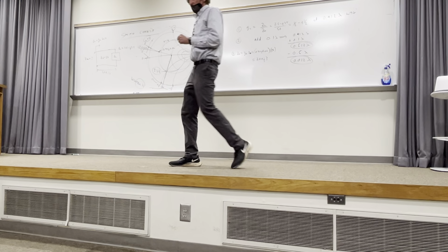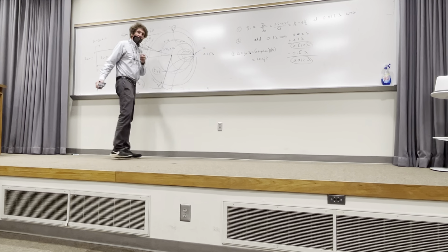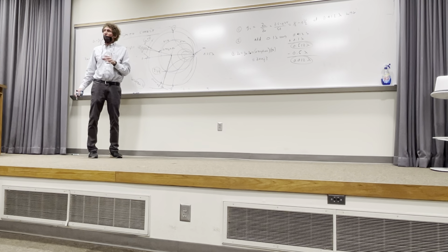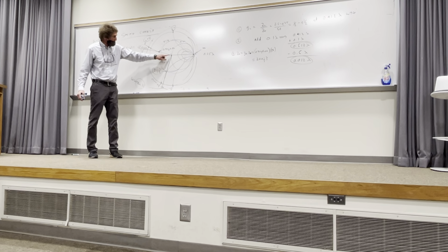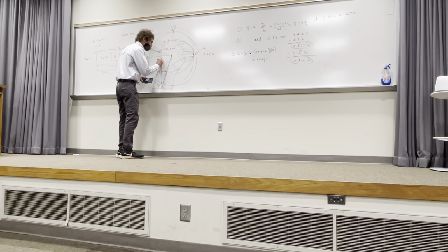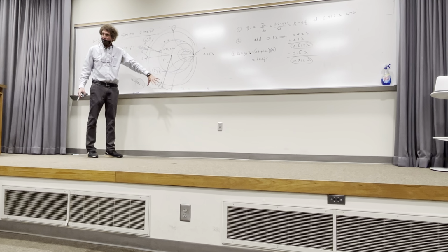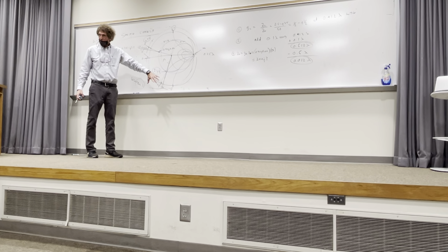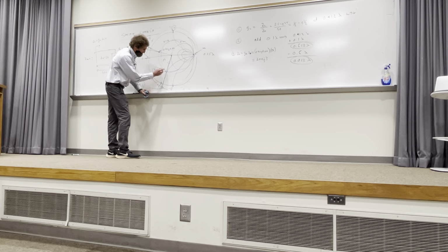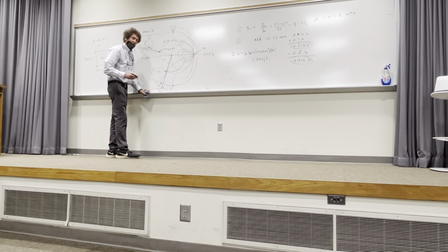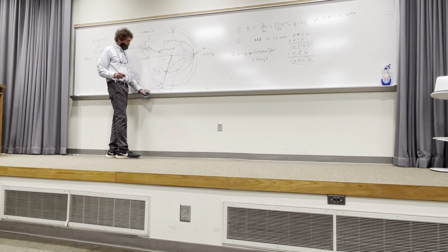What would the VSWR be using this? First, just remember, we got VSWR, standing wave ratio, right? And I think we got reflection coefficient. Now, this length right here, that is the length of the reflection coefficient. If you take it and then measure it against the bottom rail, do you all see in the bottom horizontal, there's a thing that says SWR? You can take it and put it there, but also you're going to see an angular measurement down here. And remember, we did that with the analog, we did it with the calculator, right? So what do you get for the reflection coefficient here?